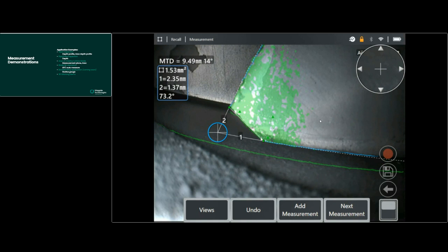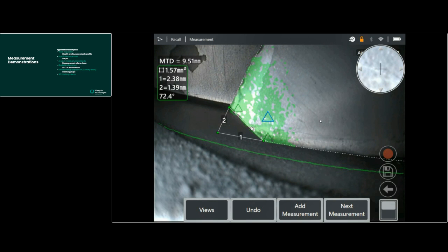Again, something just to be aware of, that when you're assigning points on a cursor on the measurement plane, you've got to be very careful on where you place your cursors. It's because it's now inferring an area or the measurement associated with that measurement plane. So it's very important to make sure that your measurement plane is correctly assigned. I flick back to the measurement plane and onto the next image. So making sure those cursors in this case are very closely positioned to where you're then wanting to perform the area measurement in this case.